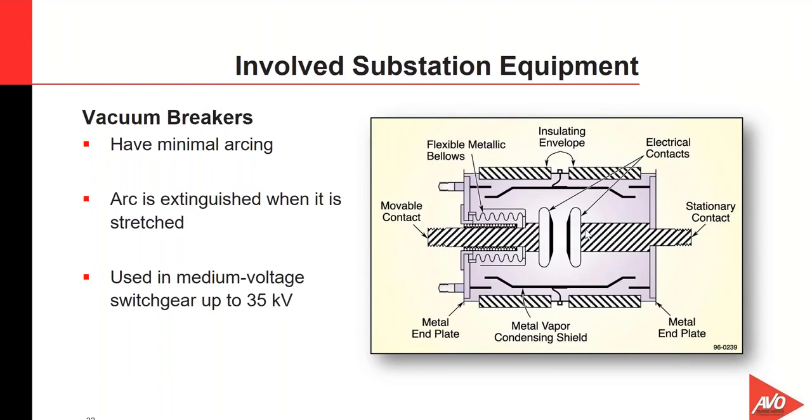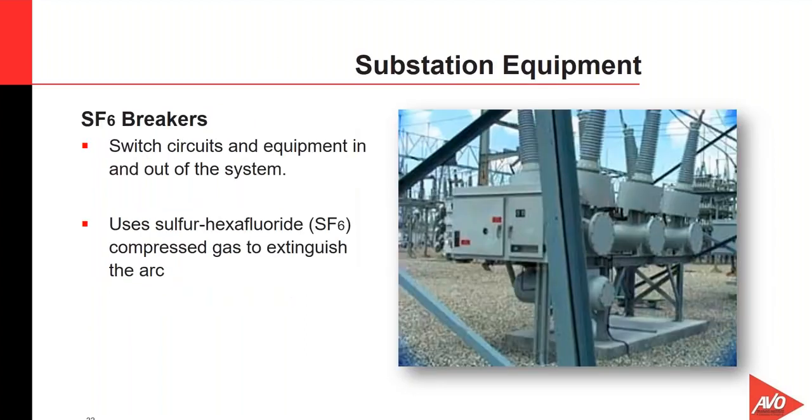So our last one here that we're going to talk about is our oil circuit breaker. And of course, this oil circuit breaker is a little kind of an older type of breaker. Most of these breakers are getting replaced, okay? But ultimately what it comes down to is we've got a movable contact down on the bottom, and those contacts are obviously going to be moving up and down in the event that we need to open or close the circuit breaker. And so the oil itself is what's going to provide that cooling and help to extinguish that arc as well.